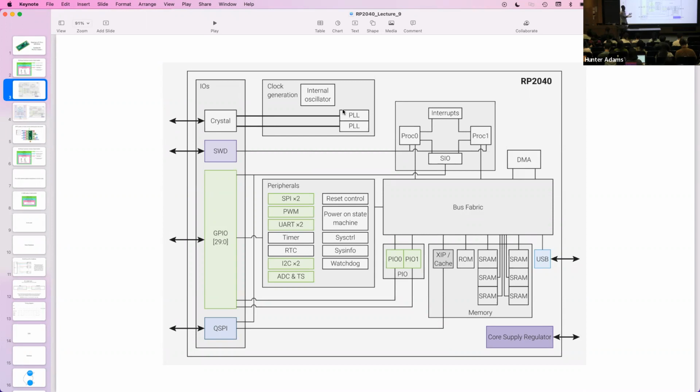You can implement that on other microcontrollers, but on a lot of other microcontrollers, doing so ends up sucking up pretty much all your CPU time. So communicating with the VGA screen and also doing some sort of interesting graphics routine can be difficult. You can run out of cycles. In this case, because we've used these PIO coprocessors to do all of our communication with the VGA screen, we can write to that screen as fast as we can manipulate the values in an array. So writing to the VGA screen becomes really fast for us because of these PIO coprocessors.